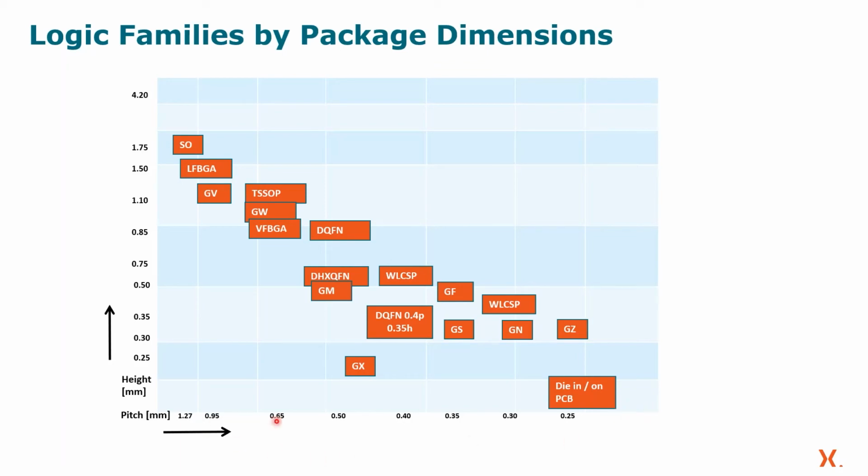Please note, however, that as you tend to get lower, the pin pitch drops at the same time. So this is decreasing pin pitch as we go across to the right. A smaller, lower height package tends to have smaller pitch devices on them, which may require some special soldering and special handling. But again, if you're looking for a logic solution, not much height for it, here's a good way of looking at the technologies which are available to support even those applications.